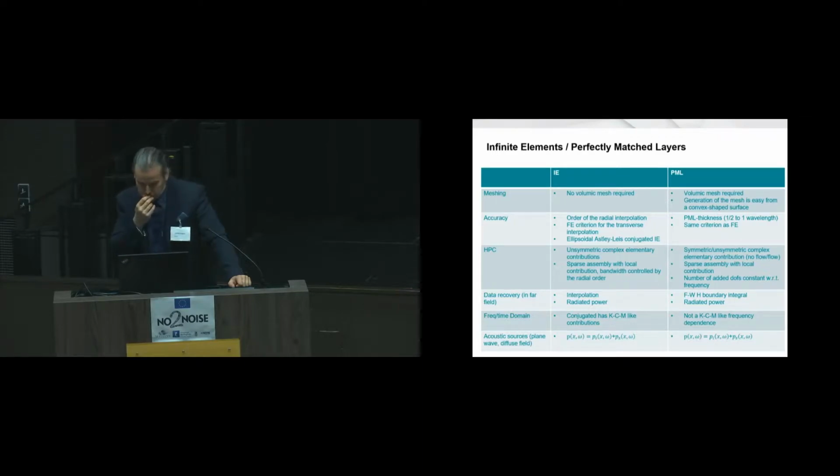And when you combine the two, basically, we found out that PML is more interesting at high frequency, infinite element is more interesting at lower frequency, and naturally when you have something like that, you tend to try to implement some automatic conversion from one condition to the other, depending on the frequency, and that's what we have done.